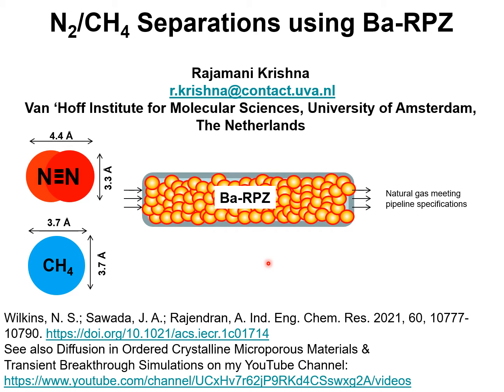If thermodynamic coupling effects are ignored, the overshoots are not realized and the separations are a lot poorer. For background to the theory of the Maxwell-Stefan diffusion equations and the incorporation into modeling of transient uptakes and transient breakthroughs, see my presentations on these topics on my YouTube channel.